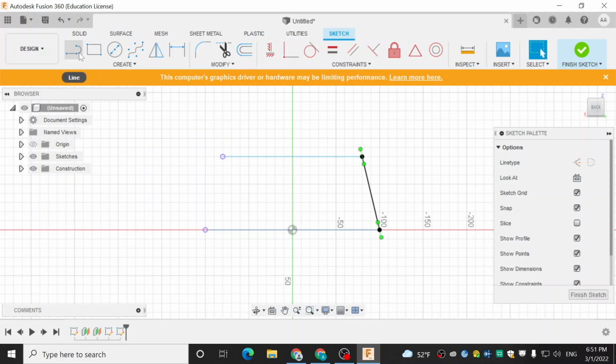So let's go ahead and create a line. And we'll put this line directly in the middle of these 2 purple points here. Because I drew mine centered on the origin, I can just select the origin and draw straight up. You'll notice as I'm drawing, it'll tell me that I'm perpendicular with this little blue perpendicular constraint symbol, which we went over last week. This line does not have to bisect anything. It doesn't have to connect to anything. It just has to be present in the middle of your drawing. So I'm just going to select a random spot in the middle here.